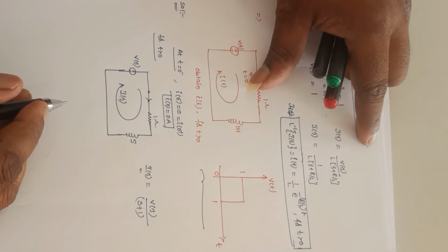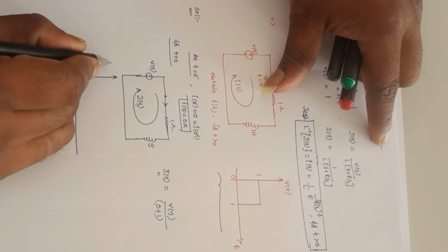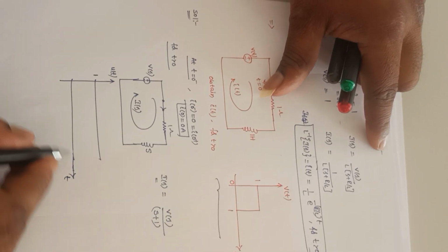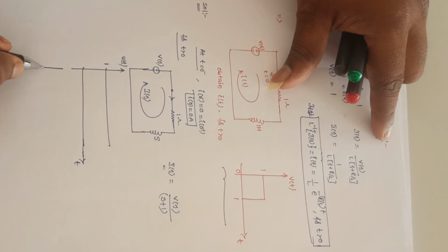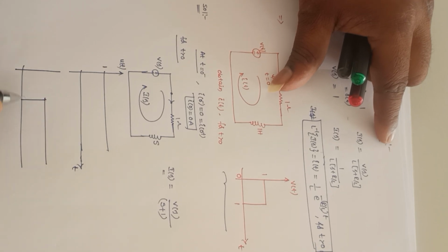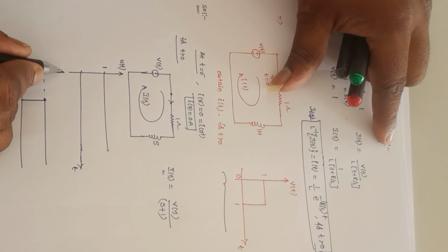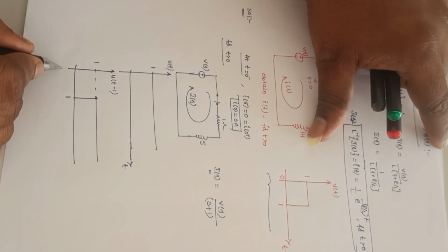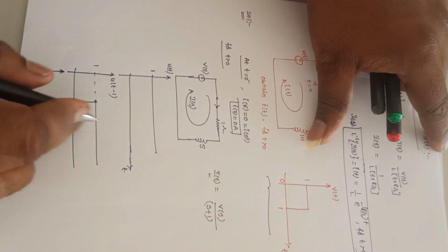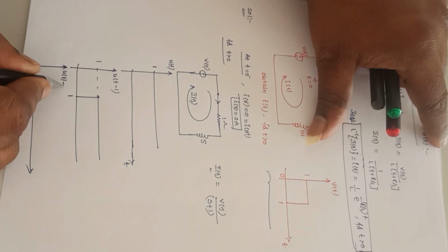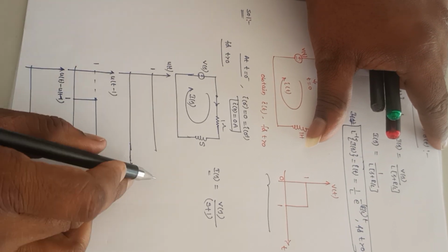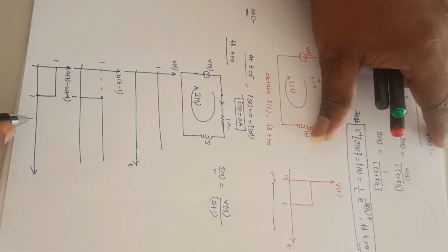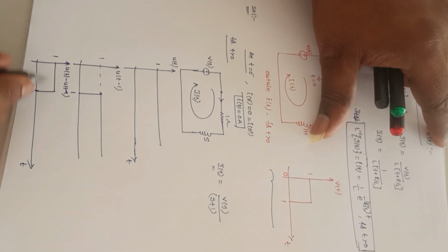So this signal I can write as follows. This is u(t), the step function, which is 1 for t greater than 0. Now this one, with magnitude 1 and pulse width 1, is u(t minus 1). The u(t minus 1) signal is like this. If I subtract this signal from this signal, that is u(t) minus u(t minus 1), then from this total I will get only this signal. So this signal I can write as u(t) minus u(t minus 1).